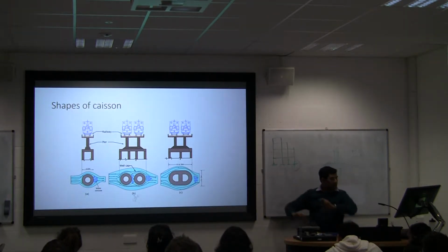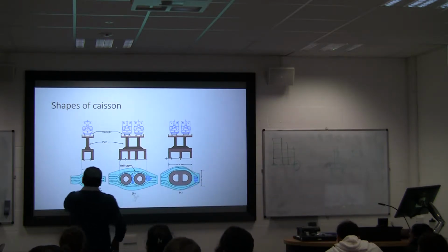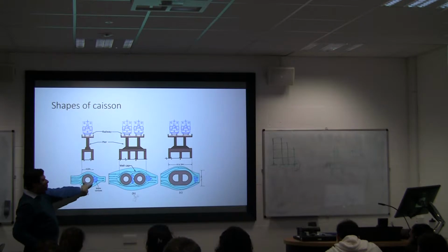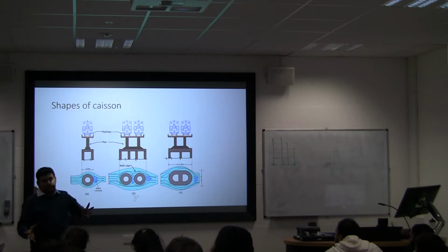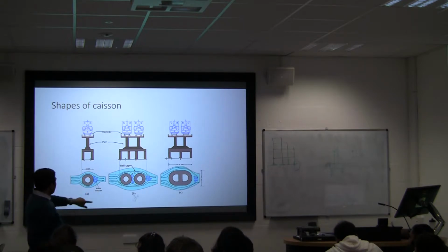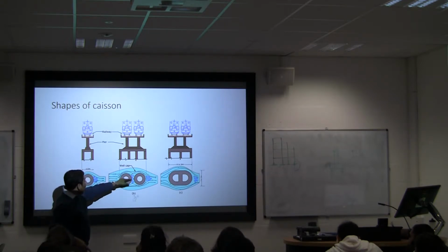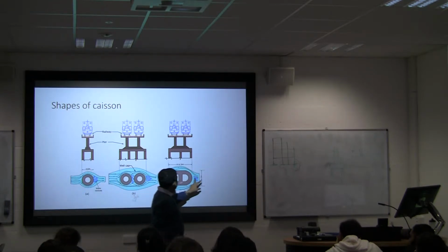The typical reasons are, if you have one large caisson, like a 12-meter diameter, quite a large thing, and you have a single track railway, you can put one. If you have a double track, you can either do two circular ones, or you can go for a double D.